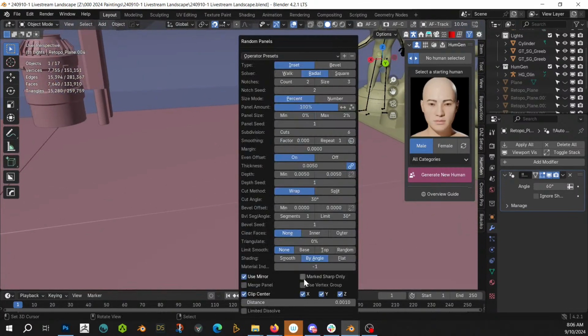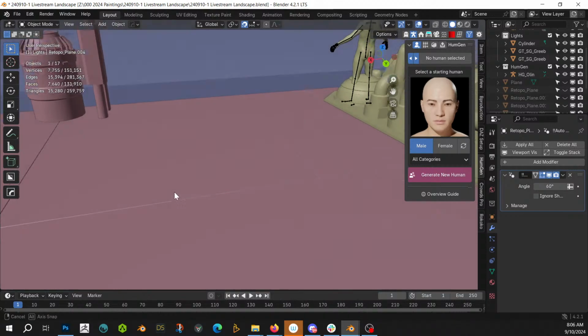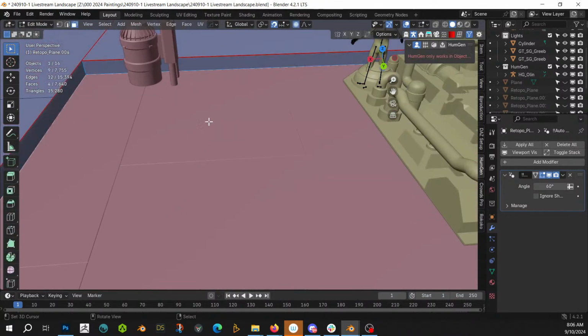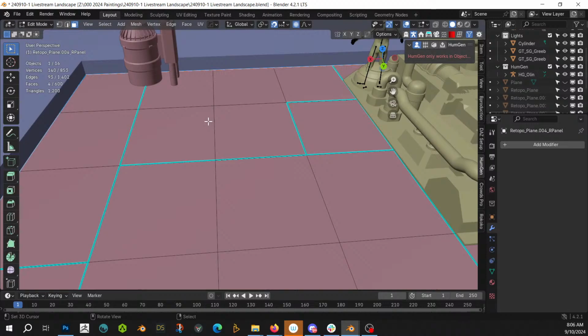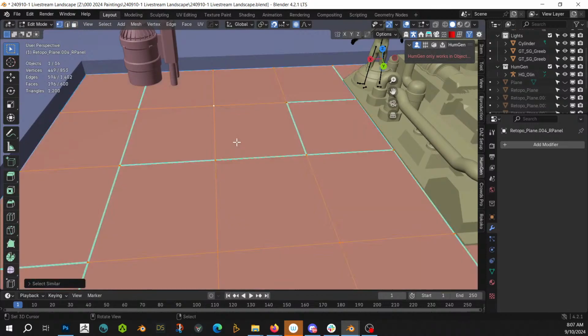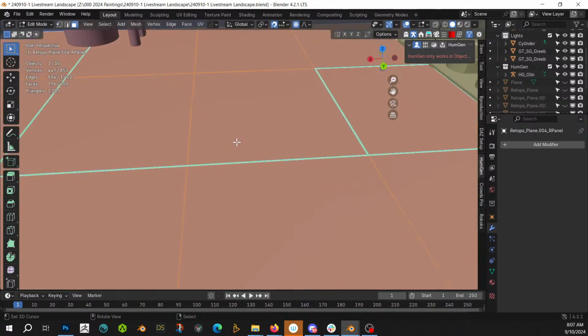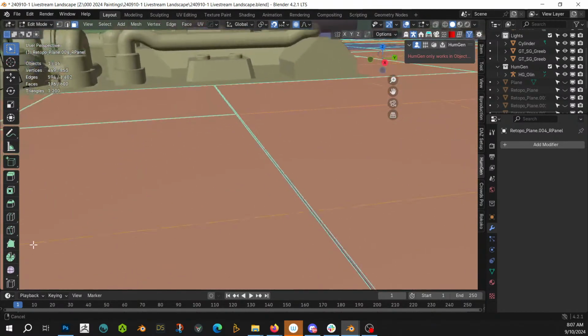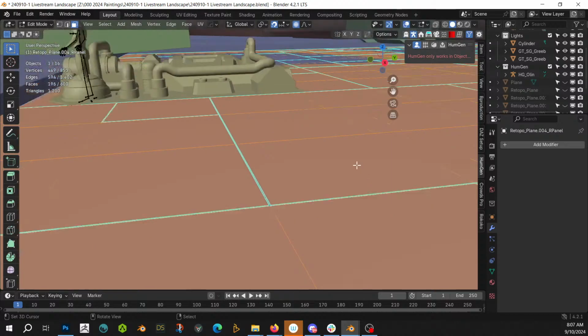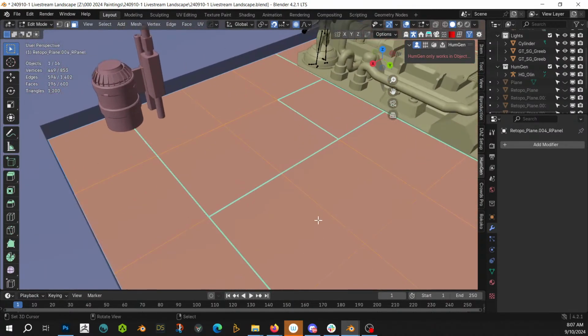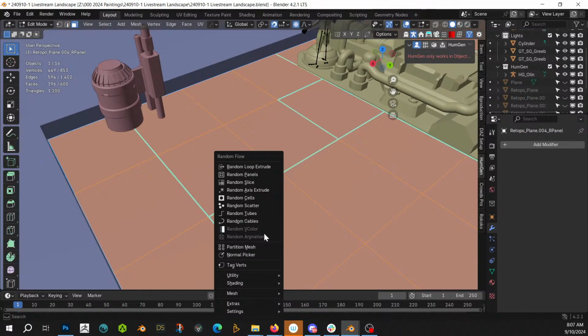F9, I want to use vertex group so I can grab the tops on them. Cool. Good deal. 1, Shift G, vertex group 3. That's the tops, right? Yep. Okay, good. Let's add, just for fun, we haven't done these in a while, panel screws.